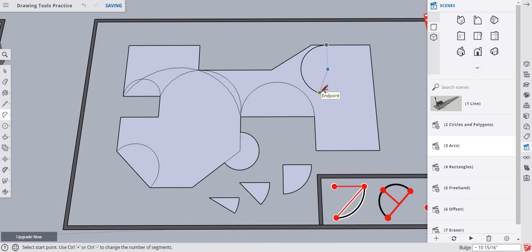We can do it again starting here, and then we want to finish the edge here, and then grab that cyan line again. So we get this super smooth line that would smooth here, smooth to here, and then smooth into there. Another thing with the 2-point arc tool is we can get lines that are tangent to 2 sides on a corner. So we go on the edge, around like this, and we'll get this magenta color. You can see that magenta right there.